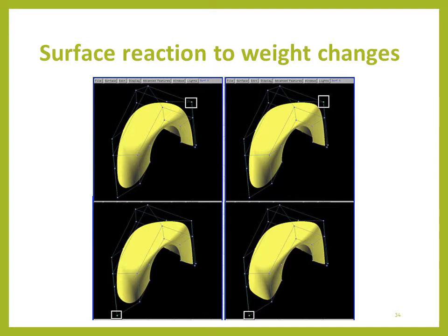But when I set the weight to 0, the whole control point is nullified. The line is basically a straight line between two control points, and the control point whose weight I have set to 0 is completely nullified. So this is a very important property of NURBS curves. We can adjust the weight to adjust our surfaces and curves, right? And now we'll discuss the derivatives.